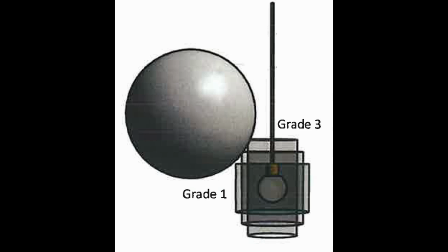We'll look at how geometric complexity impacts file size and speed, how metadata and 2D line work enhance model value, and why BIM should prioritize structured information over AutoCAD-style drafting habits. The key concept introduced is grading of components, building models in stages, using simple placeholders first, and only increasing detail when it is genuinely required.